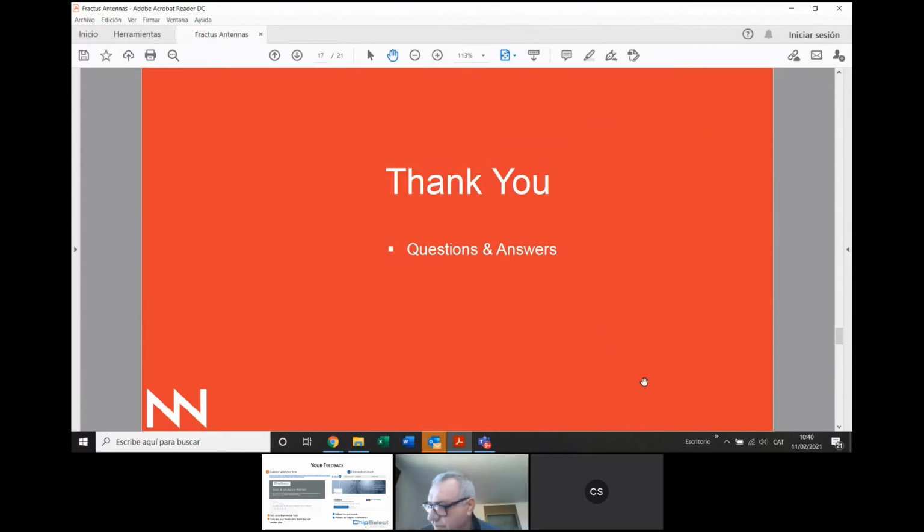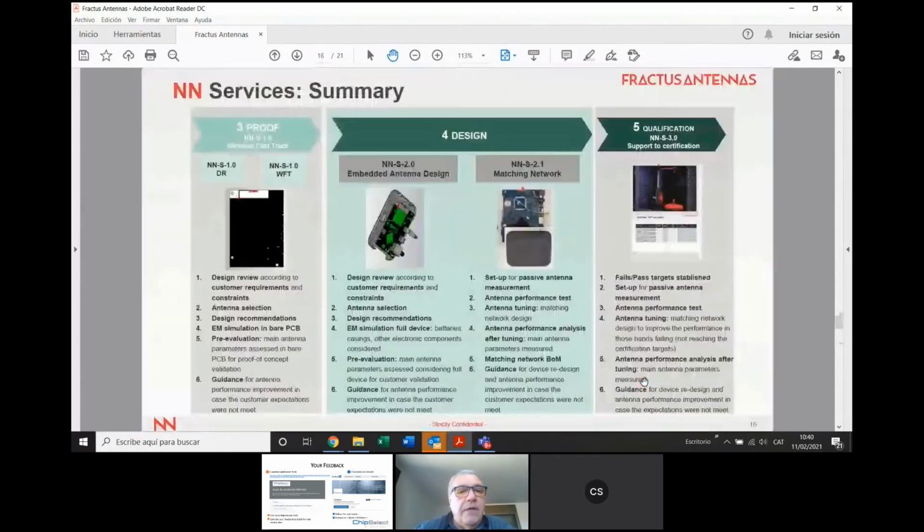Okay. And the clearance area is a parameter that you are giving based on the first fast track report? Correct. We are giving that. You can see here in this slide a report where you see the antenna location, the minimum clearance area requirement, and the PCB size that is given by the customer.